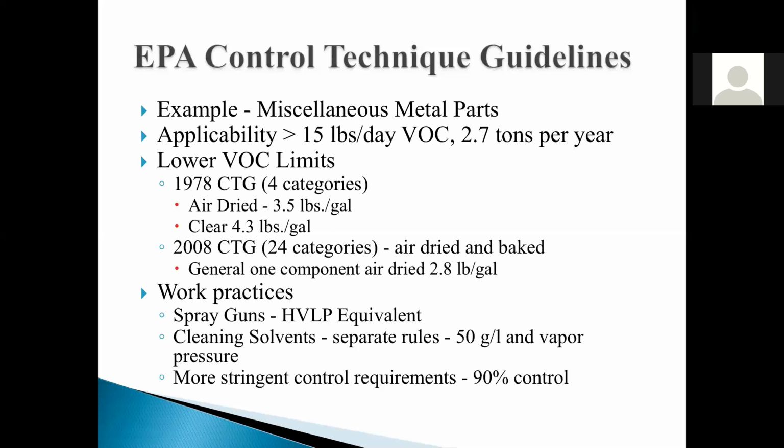Before you coat, you might wipe the substrate down. Sometimes there might be some discussions in these rules. However, there is a whole other suite of regulations called industrial solvent cleaning regulations that states have been adopting over the last couple of years that will get into, again, the solvents used to wipe down the substrate, the type of solvents that are used to clean out the spray guns, et cetera. And those could be, you know, 50 grams per liter. They could have a certain vapor pressure requirement. So just want to throw that out there, that the type of cleaning solvents that are used in facilities could be regulated as well.